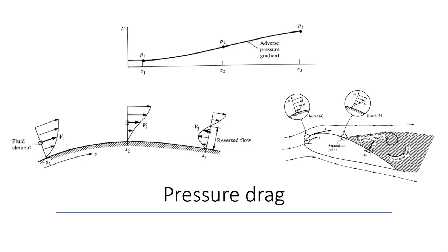As the fluid flows past the surface, static pressure and dynamic pressure, which is proportional to the velocity squared, vary at each point as predicted by Bernoulli's equation. If the static pressure increases in the flow direction due to the nature of the flow, the fluid particle motion is retarded even more. This phenomenon is known as the adverse pressure gradient.